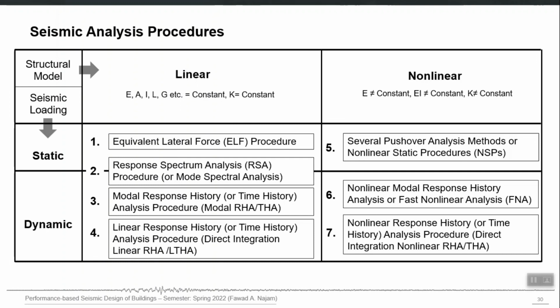On the other hand, we have linear static analysis, where the computer model used for analysis is linear. It is following Hooke's law forever, and at the same time the applied loading, seismic loading, is assumed as a static loading or is represented as a static loading, right. So the ELF procedure is in this domain, linear static analysis. So we use a linear computer model here, and we apply some static forces which are representative of the future earthquake loading to our model.